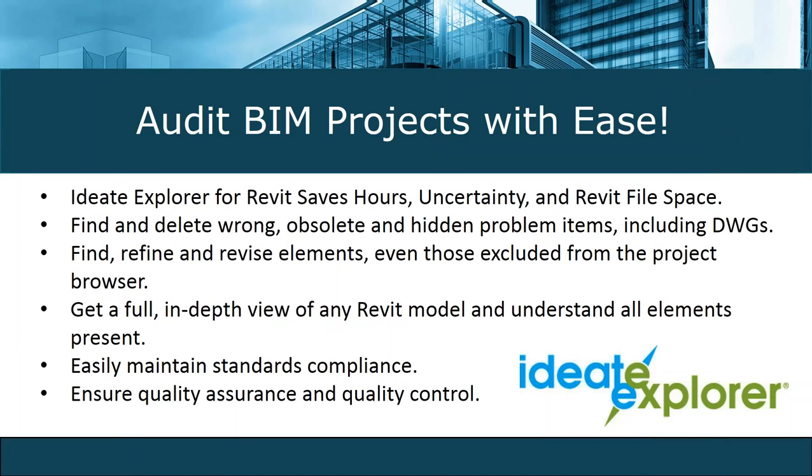So the first solution that I'm going to talk about today is called Ideate Explorer. And Ideate Explorer is a model browser. It's showing you all of the instances or elements in your Revit project, which is very different than the project browser. The project browser in Revit out of the box shows you some families that have been loaded into the project or template, but it's not giving you a comprehensive list of all of the instances and pieces of information in your project.